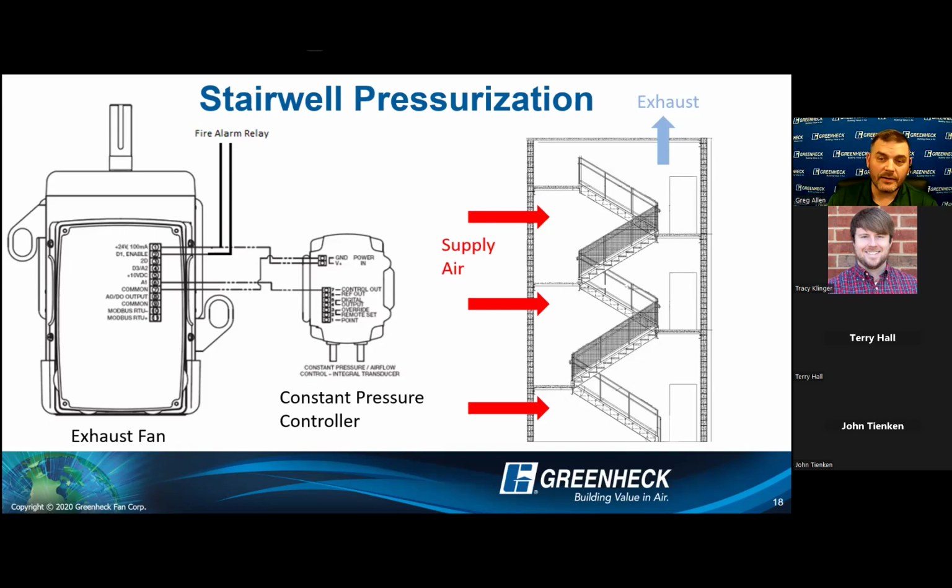So only when a fire alarm goes off does it actually start controlling the pressure in that space. Like I said, there's 100 ways to get each of these done. I'm just showing you standalone controls and a way to look at it and think. But again, I'm just using a 0 to 10 volt signal as my communication method.